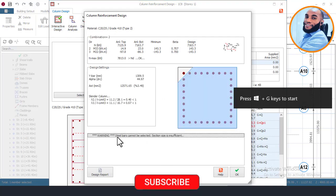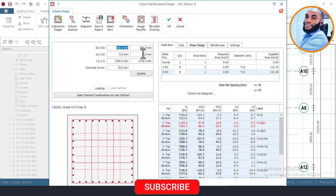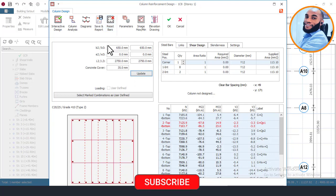And this is the failure: the size will be increased. I'll say okay, and then come here and increase it. But most times it might not be the size that you're meant to increase. You can't just go and increase the bar size and all that. So make sure you check first why it is failing, and then say update, and then click on reset bars here, and now there's a stage where I'll show you where to click on this area.